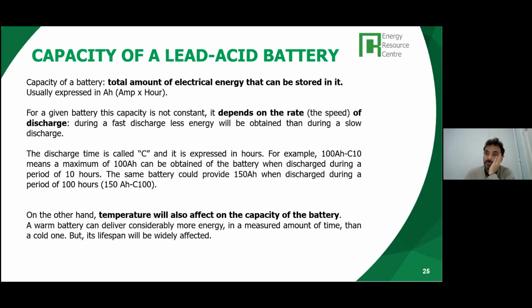So it's a combination of the current that it will give us and the time during which this battery can give this power. Now, the situation is that this factor, the capacity, is not proportional, is not constant. The capacity depends on the current that we actually will be drawing out of the battery.